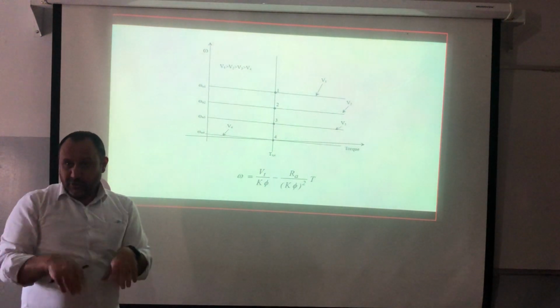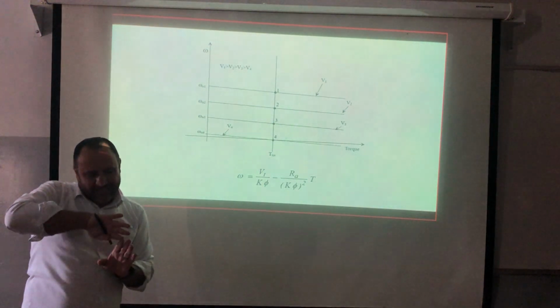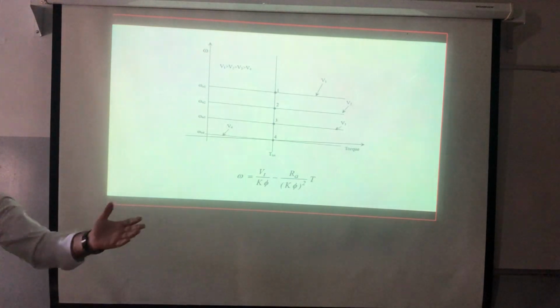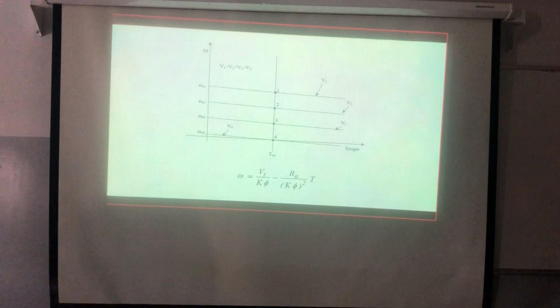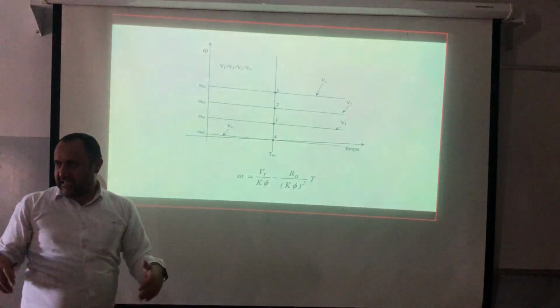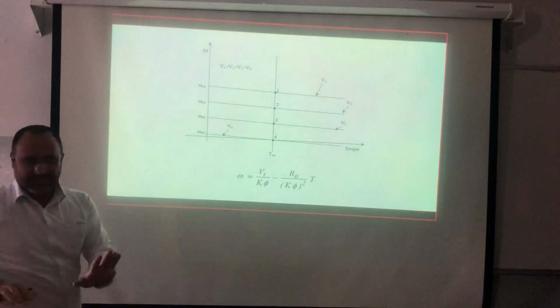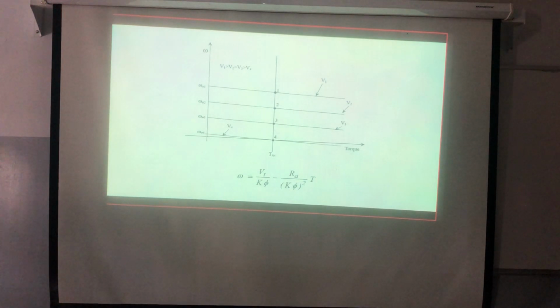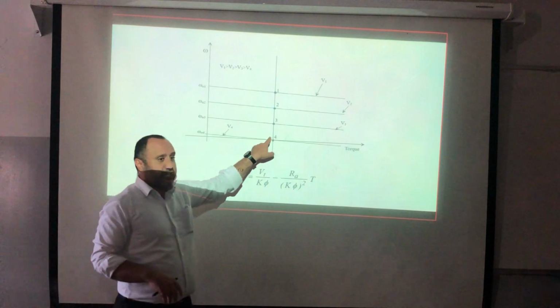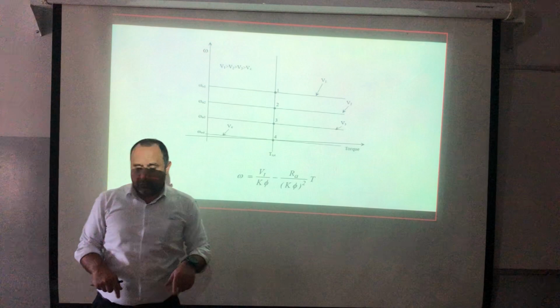So let's assume that I'm having a separately excited machine. Otherwise, I will affect the field, and there's a relation between the field and the armature circuit, and the relation will be non-linear. Let's assume I'm doing armature-controlled, separately excited. So I will adjust the voltage such that the machine is at hold position. How to calculate this one?